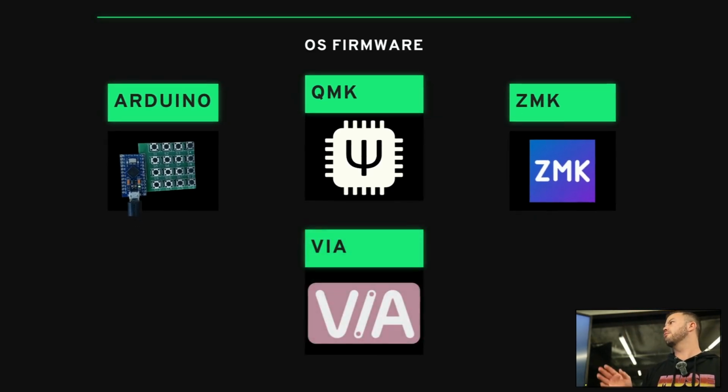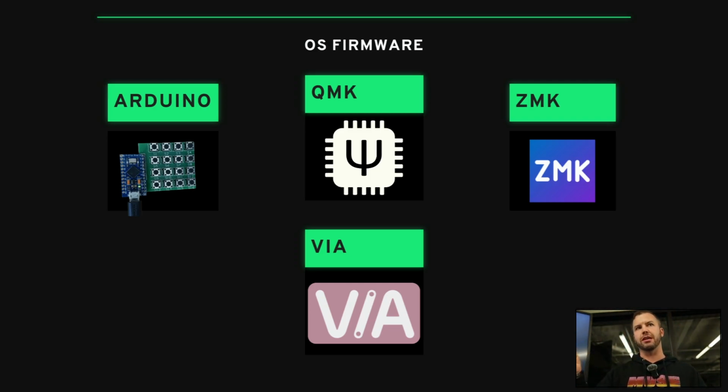Now there is a feature that can be turned on in QMK that allows you to have a GUI on top of QMK, called VIA. I don't know if you've ever heard of Firmata for Arduino, but the idea is that you can send commands to the microcontroller after it's been flashed. So what VIA lets you do is reconfigure where your keys are even after you flashed it. Because with QMK by default, every time you want to switch one key, if you want to move the A to the S and the S to the A, you have to rebuild and then re-flash it to the chip. VIA lets you do it via a web interface or a desktop app, and it changes it in real time on your keyboard, which is pretty convenient.